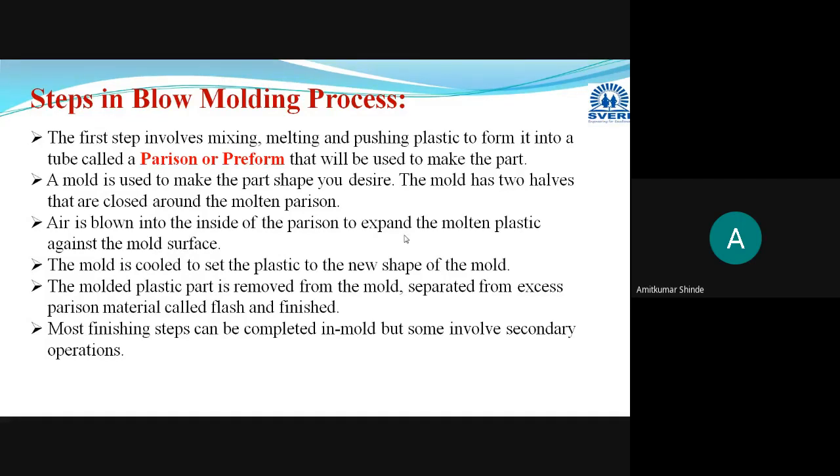Through that you have to blow the air against the mold surface. Against that mold surface we are blowing it. Then one cooling arrangement will be provided in that mold cavity. Due to that cooling, whichever molten plastic or preform we have will get solidified.